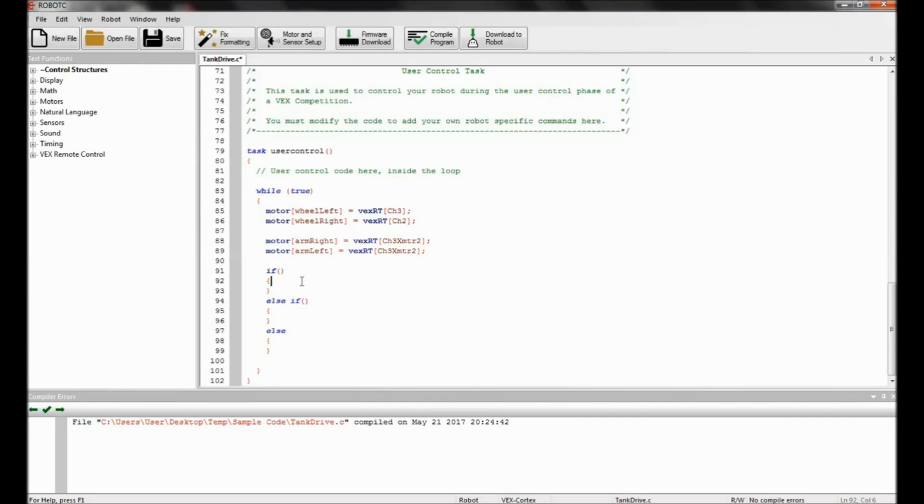And this last step of having no movement is kind of crucial to programming motors in Robot C, because in Robot C, motors will continuously run at the last command given to them. For example, if you were to set the power level equal to, let's say, 75, it will continuously run the motors at 75 until you set them back to 0. So keep this in mind for programming, as it'll become very important.